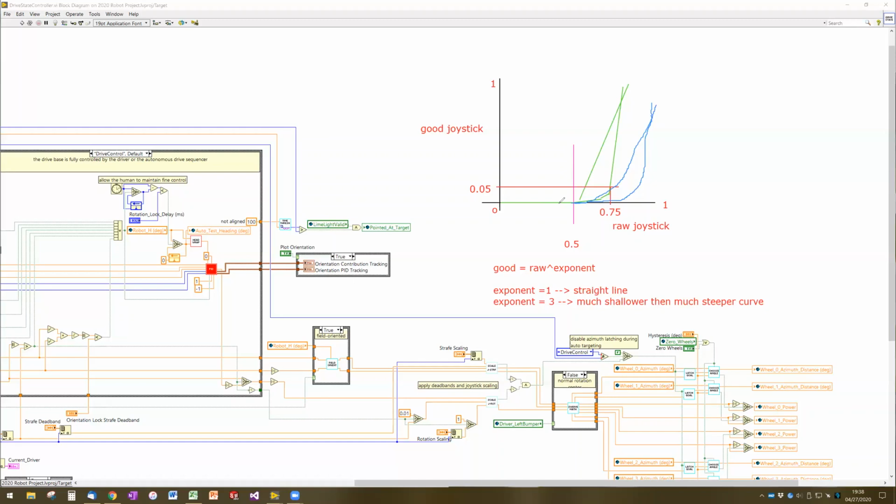What this allows is that even if the robot is going slowly, for situations where the robot's going slowly but you've told it to accelerate, you maintain your fine control until the robot actually gets up to speed, versus losing that fine control as soon as you tell it to accelerate. So that's another tweak that we could consider making.